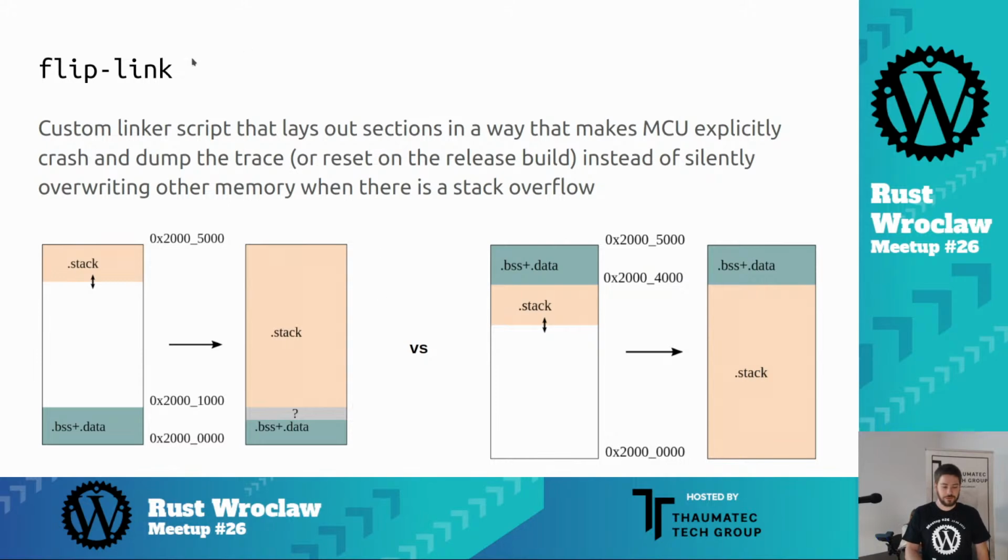So flip-link also does some linker script magic, which reorders the sections in a way that BSS plus data is here, the stack is here, and if the stack grows to the point where there is no more RAM, the MCU will throw the hard fault exception.